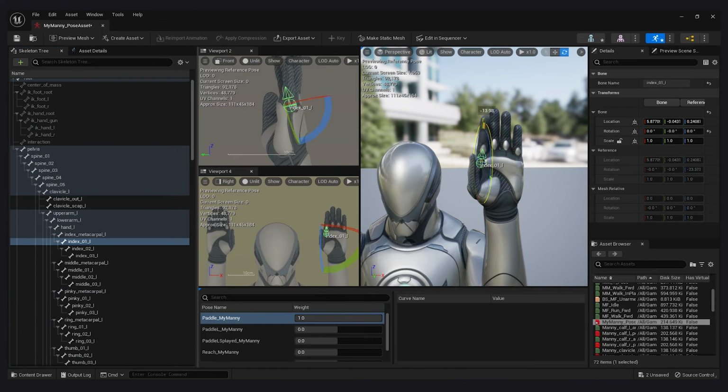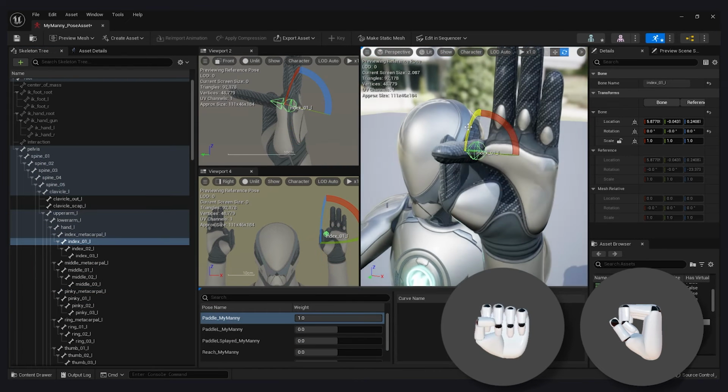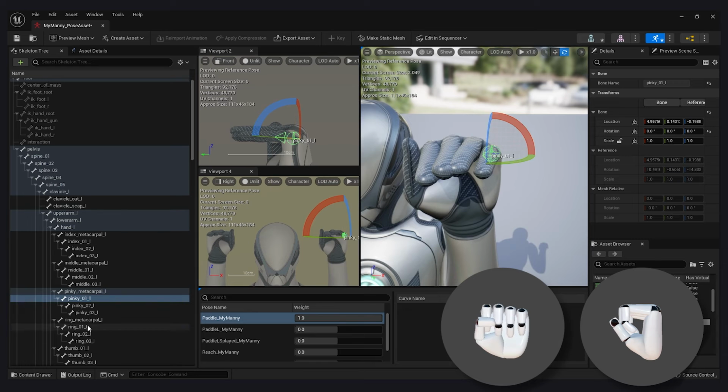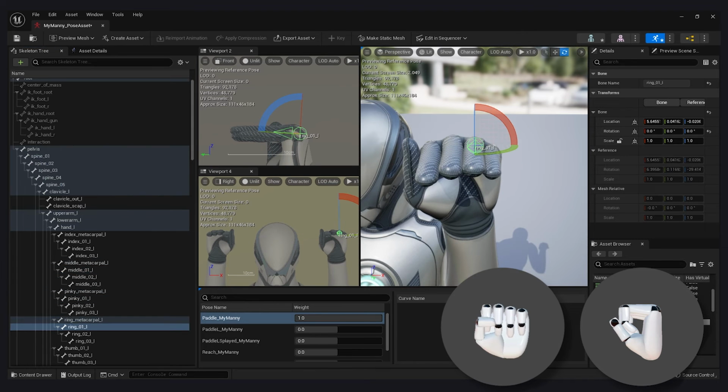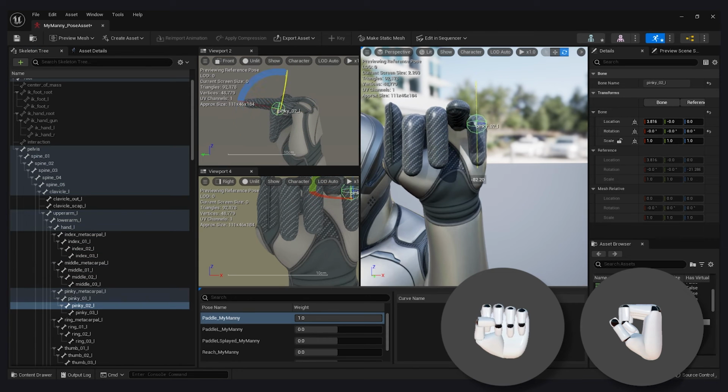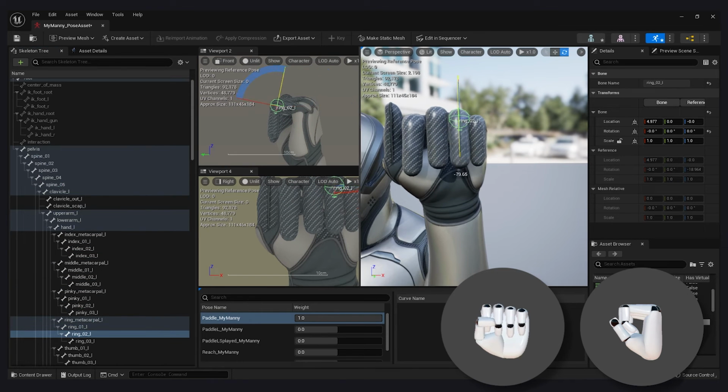For our last pose, we have fist. For this pose, we want to start from pedal and have all the finger joints maximally curled, the thumb base joints curled so that the thumb aligns with the side of the palm, plus the maximum rotation of the plane of the palm by the base of the thumb, plus maximum curl of the thumb tip.